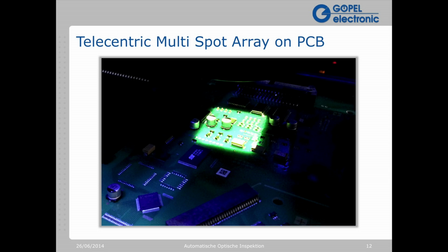So we actually scan the array of white lights across the board and effectively produce more sample areas by sampling and taking measurements as this array of light spots is being moved across the board. This scanning method also is part of our speed capability. Scanning this array of spots across the board rather than stopping and starting allows us to be very fast.